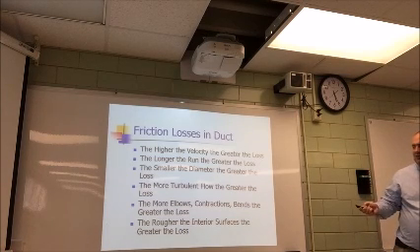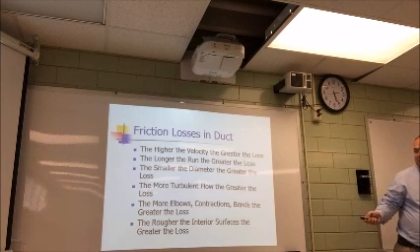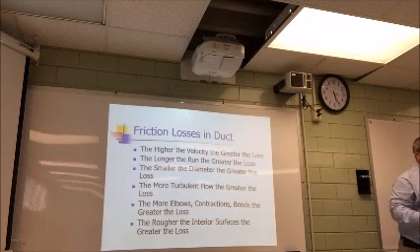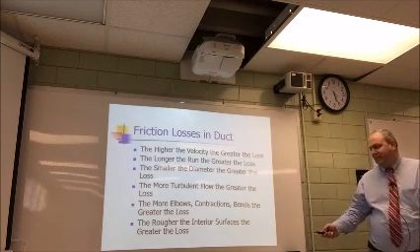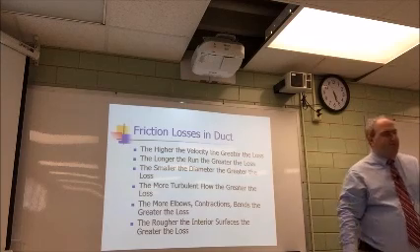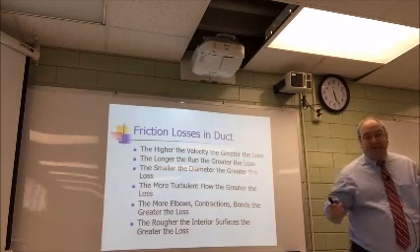So the smaller the diameter, the greater the loss, and again, the more turbulent, the greater the loss, and the more turns you have, the greater your loss. So it's trying to help you with design, and the rougher the interior surface, the greater the loss. That's why if you ever look at ventilation, it's all smooth.